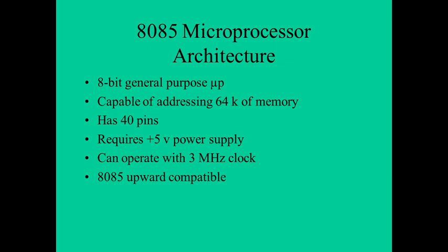This device has 40 pins. It requires +5-volt power supply and it can operate with a 3 MHz single phase clock. 8085 microprocessor is upward compatible with that of 8080A, meaning that the 8085 instruction set includes all 8080A instruction set plus some additional instructions.